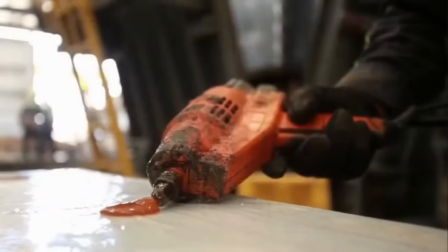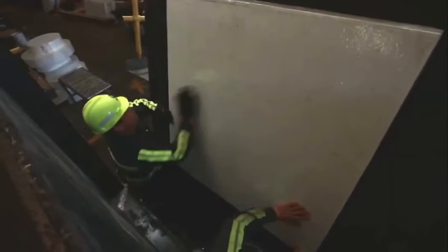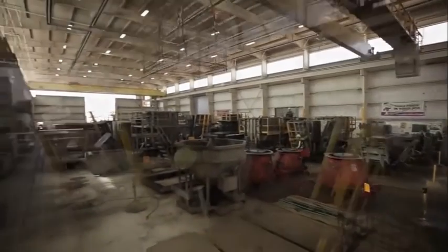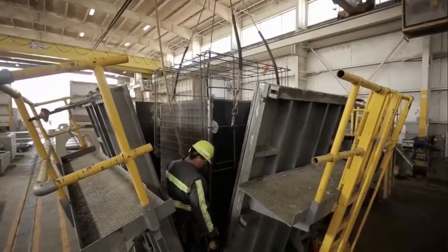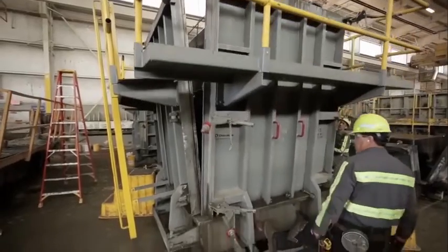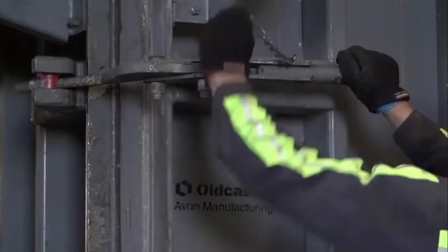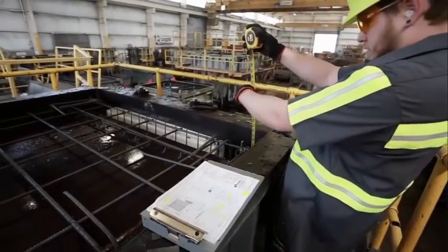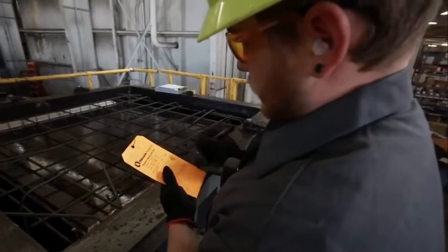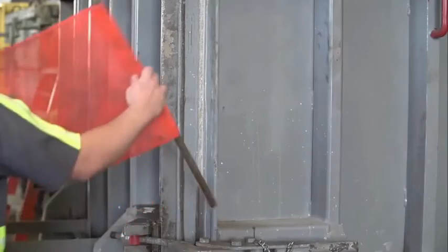At this point, all openings, cutouts, or embedded items are secured to the form. Then a form release is applied to each surface to ensure the final product can be easily lifted from the form. Now that the form is prepared, the overhead crane is used to pick and place the cage onto the core of the form. Care is taken to ensure that the reinforcing cage is stable for transport to the form. Once setup is complete, A certified quality control technician will conduct a pre-pour inspection to ensure conformance with the approved shop drawing. Upon satisfactory completion of this inspection, the technician will sign off and flag the form indicating approval to